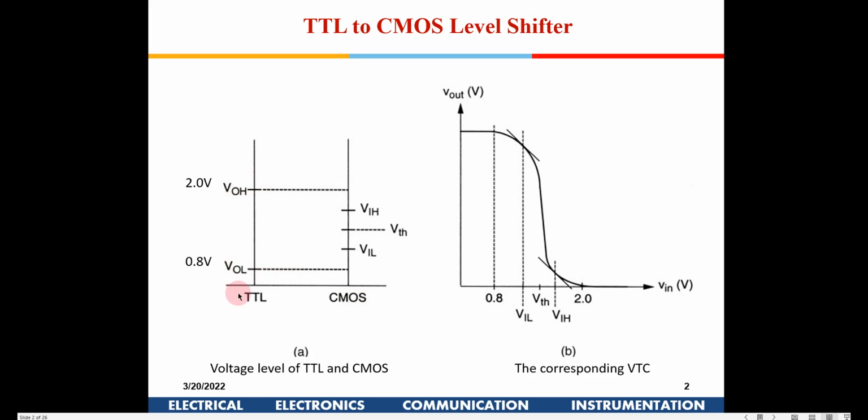So the signals coming from the TTL logic family, if you see here, the VOL and VOH for a TTL are 0.8 and 2. So you don't get a rail-to-rail output in TTL, which we discussed even in our first class. So the output for the low condition could be anything between 0 to 0.8, and the output high could be anywhere between 2 to 5 volt. Okay, so it is not symmetrically placed across the VTC, and there is a band of voltages for VOL and VOH. For low, the range is 0 to 0.8, and from 2 to 5 is the high voltage range.